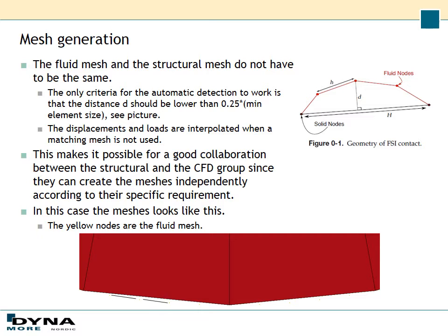And I mentioned before that the structural and fluid mesh do not have to be the same. And for the FSI criterion to work, the distance d here in the picture must be lower than 0.25 times the minimum element size between the fluid and the solid.